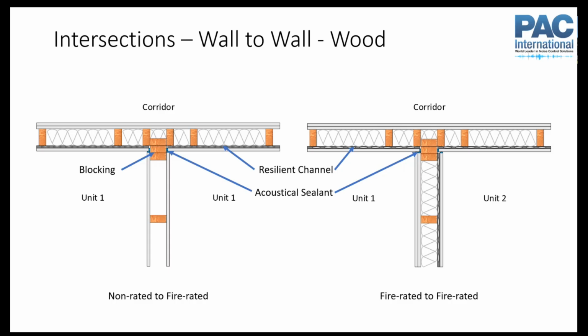If you have a gap here because your drywall is discontinuous, you can intersect your drywall with wood blocking because it counts as fire blocking. So you want to pay attention to this detail here. If this is a rated wall, then we need this fire blocking both for this path and for this path. So you kind of have to have this beefed up 3-stud corner here.